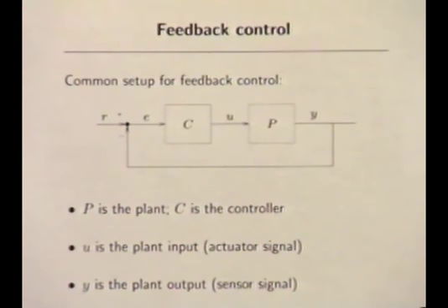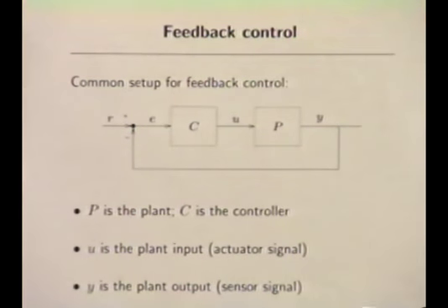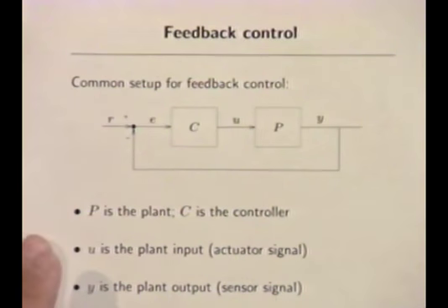So the controller now says, no error, no problem, I'll go back to the open loop control, and it increases the power again. So what's happening is this feedback thing: it keeps adjusting. That's the idea. If it were not continually adjusting, if it made one adjustment and quit, you would set K equals 1. That's what you would do.